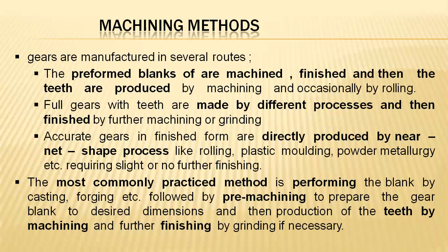And for these blanks of different dimensions, the teeth are produced by different machining processes, either the milling process or the broaching process or different cutting processes which are suitable for getting the desired tooth profile or its diametrical range by maintaining a particular thickness, depth, sharpness, and tips. Later, the finishing processes are done over it for removing the rough surface finish, either by the finishing process or else by grinding processes if necessary.